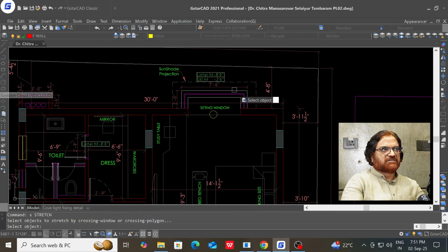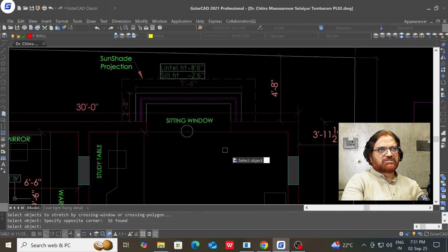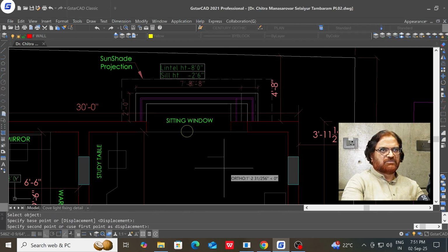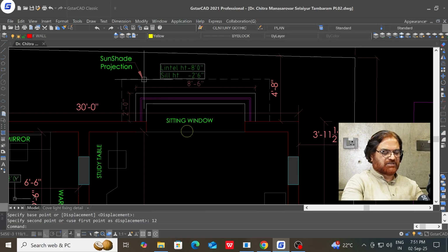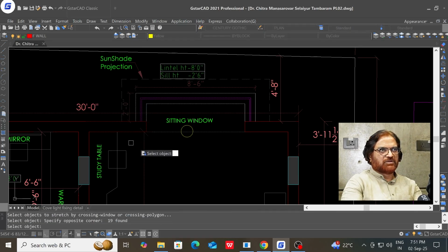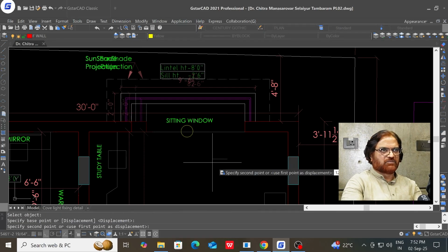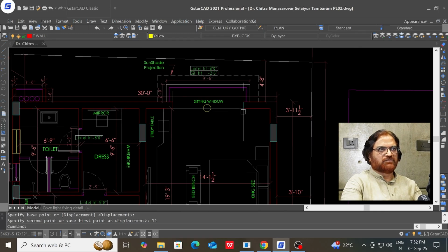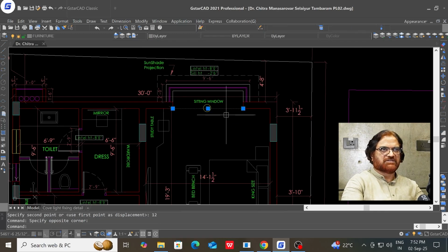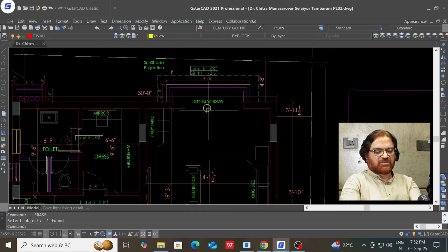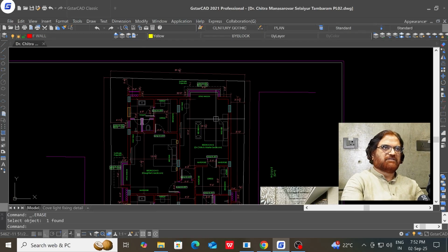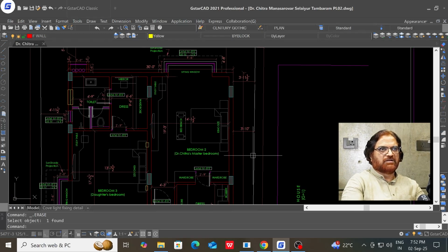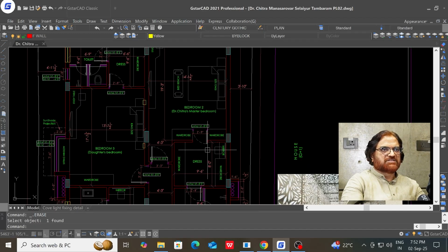Then coming to the master bedroom, again I would like to see this as big as possible, because this is our signature feature. So this will also be a very nice thing to do. You should have at least another 1 foot. They extended by another 1 foot, 2 feet. So 1 foot on either side I'm extending. So you have at least 8 feet here. So either it accommodates a nice sofa, or it is a sitting window as we regularly do in our houses. So this is a very nice bedroom of nice size. You can have some nice seating here.